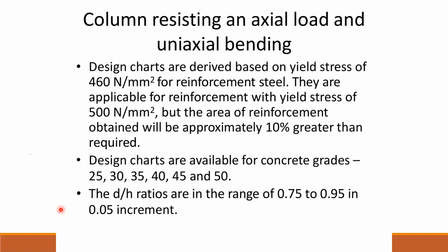But today, mostly steel has higher strength, 500, 550, etc. So still you can use the same one. They are applicable for reinforcement with yield stress of 500 megapascal, but the area of reinforcement obtained will be approximately 10% greater than required.